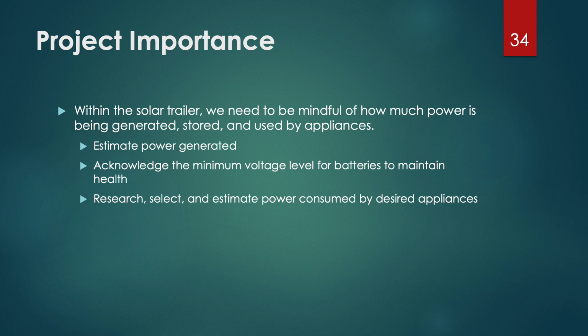There are a few key things that are really important for our solar power trailer project. We need to be mindful of how much power it can generate, store, and be used. First, we need to estimate the power that can be generated in one day, and we need to acknowledge the minimum power for the battery to maintain good health. We also need to estimate the power consumption by the appliances that we plan to use in this trailer.